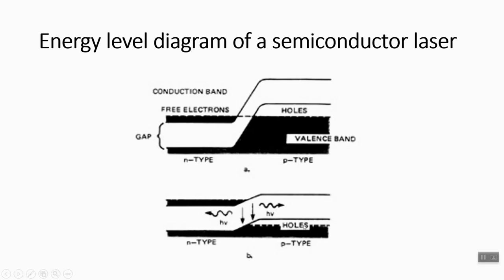The electrons and holes recombine and energy is given off in the form of photons. The energy of the photon resulting from this recombination is equal to the energy associated with the energy gap. This energy is often in the form of electromagnetic radiation. In light emitting diodes, that means LEDs, this light energy is transmitted out through the sides of the junction region. However, in semiconductor lasers, the junction forms the active medium and the reflective ends of the laser material provide feedback.